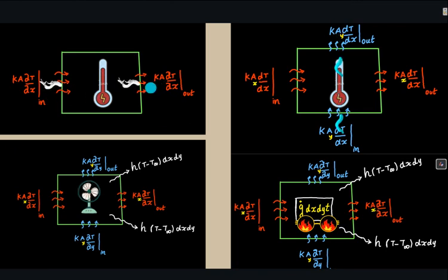And you can see the quantity of heat that is going out is directly proportional to the cross-sectional area, and also the temperature gradient at the right extreme end. So it's basically the same equation, except that you are just adding the suffix: in stands for the heat that is coming in, and out, the heat that is going out. In exactly the same fashion, you can just write the quantity of heat that is rushing in towards this calculus element from the bottom that you see here, and the quantity of heat that is going out. So it's essentially the same equation. That's the one that is represented by the blue color.